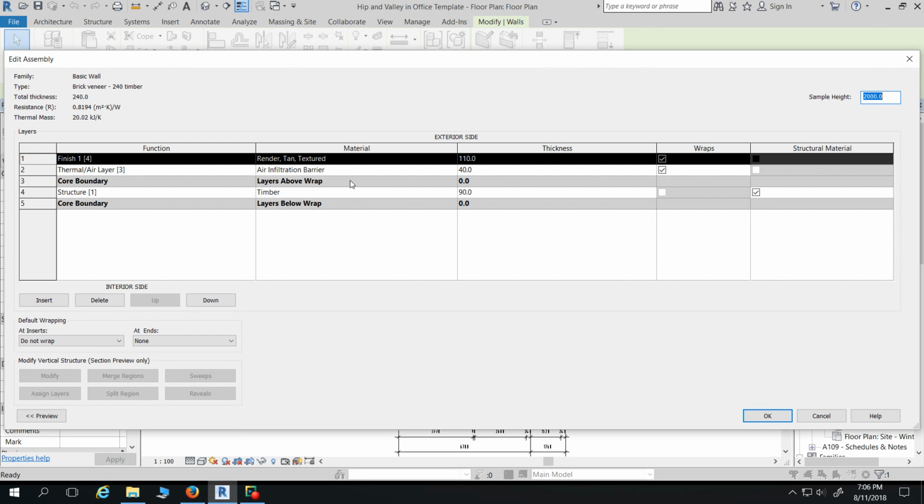Extend to core goes to either face of the stud, the core boundary. So this is how we model it at work. That's because you get an 86mm brick rebate in Australia, or in South Australia at the very least. Other states can be a little bit more sometimes, depending on what sort of footings they're using and if they're using waffle pods. It depends on what you're building; you might have a deep rebate at Blackwood Park. So that's the core boundary.